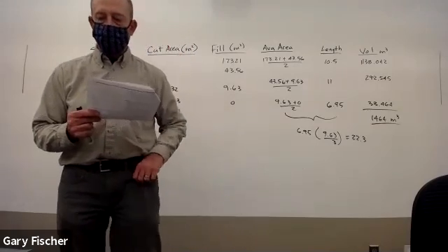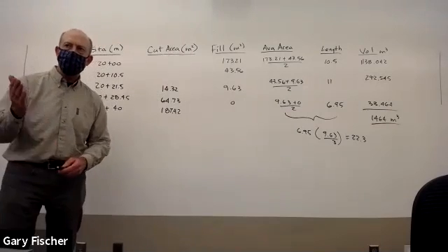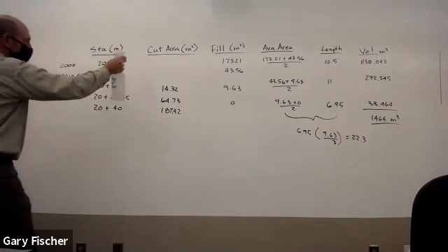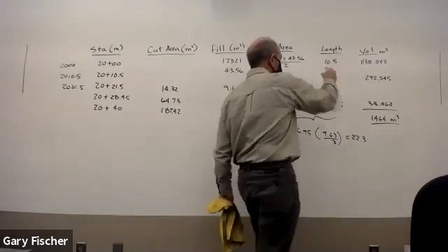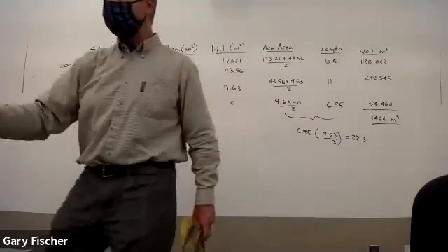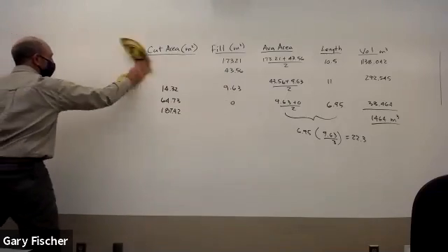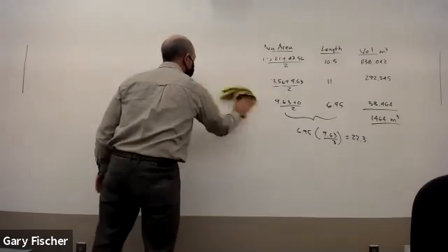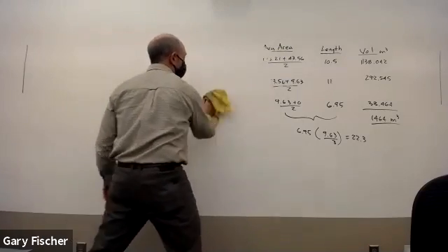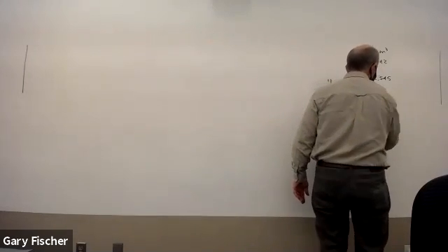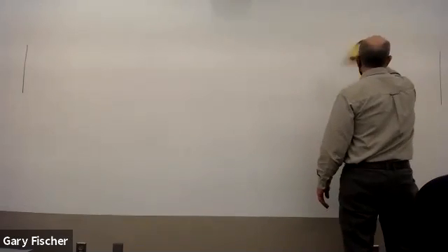And problem 6 deals with northings and eastings. Are you guys familiar with that? I've heard the terminology, and that's about it. Okay, all right. The concept is actually really easy, because you're really envisioning a grid. A northing refers to its position in the north-south direction, and an easting refers to its position in the east-west direction.